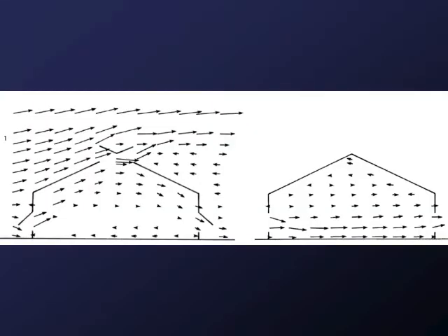What I want to talk about in the next few slides is to try to envision how air flows through the greenhouse and what that means for temperature regulation. In this example, we have side vents and we have gable vents, ridge vents. These vents are at the ridge of the greenhouse. And if you track the flow of air, air can enter the side and exit the other side. It can also enter the vent and exit the vent. To some extent, you get a general cross flow over the greenhouse. And that's not too bad. That's a decent scenario for cooling.